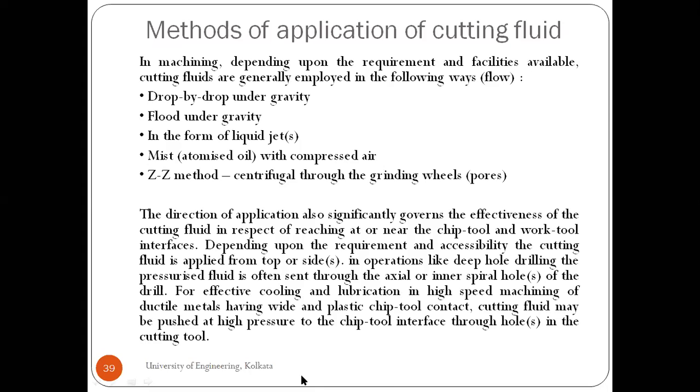So for effective cooling and lubrication in high speed machining of ductile materials having wide plastic chip tool contact, like the plastic chip tool contact which we just discussed a few minutes back, if it has a wide contact, because in case of ductile materials continuous long chips will be formed, and the maximum portion of the chip will remain in contact with the rake surface.